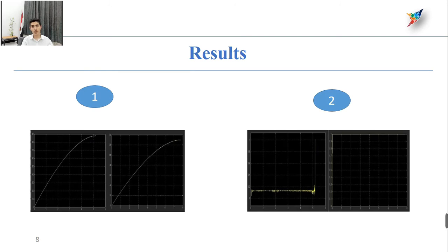Figure 2 shows that with ABS, the slip ratio is limited, whereas in absence of ABS system, it is large and equal to 1 for most of the time during the motion. With ABS, it ranges from 0.11 to 0.145 for most of the time.